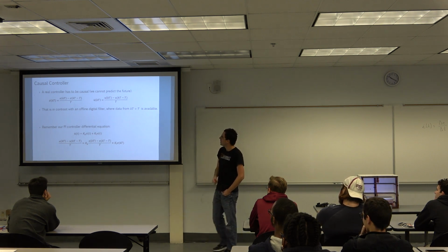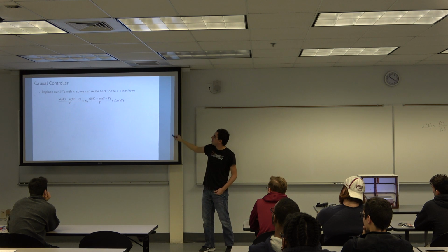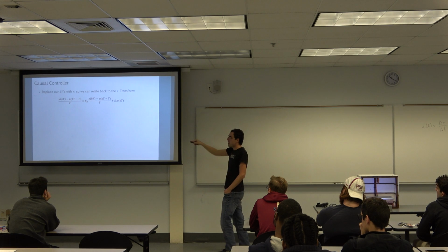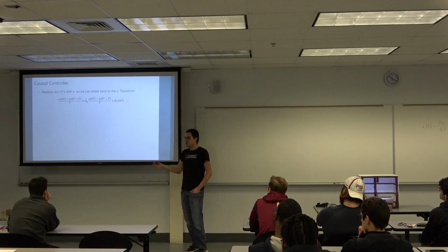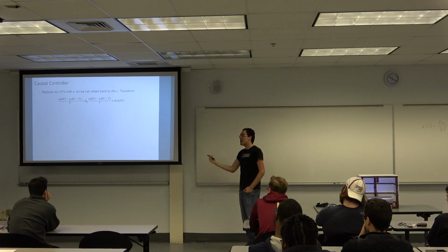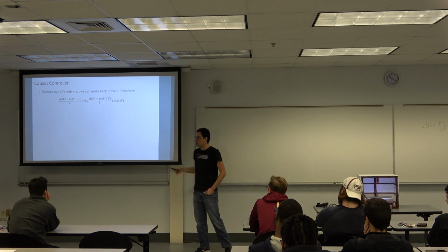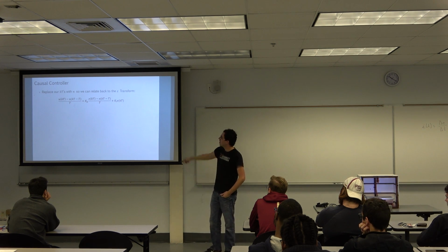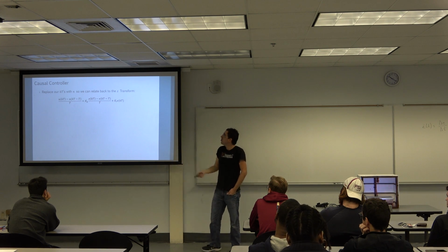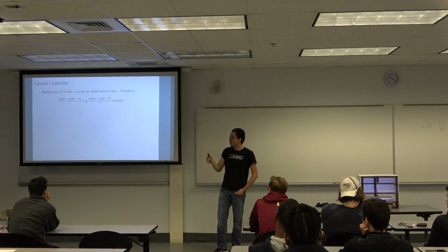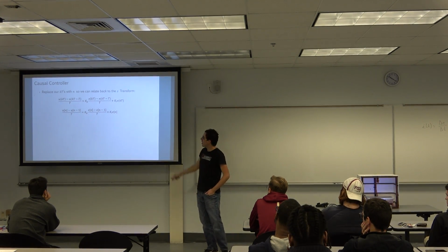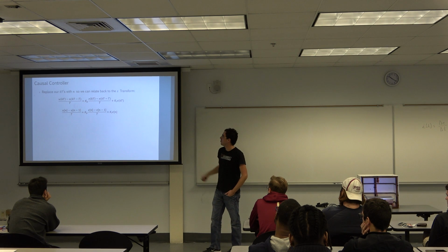Not too nasty. So I'm going to copy that expression just to have more space in the slide. I'm going to replace kT with n, as we discussed, because then we can go back to the Z transform and tie everything back together and see what the Z transform actually does in our analysis. So u(kT) becomes u(n), the nth u sample, and u(kT - T) becomes u(n-1), which is the (n-1)th sample. And we do that for e(t), and we get that.